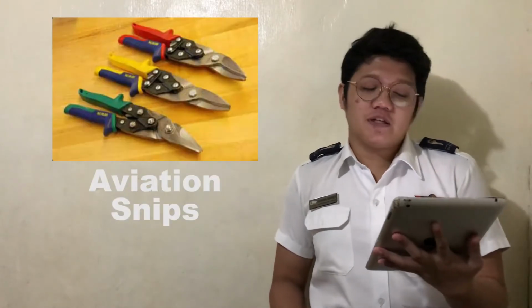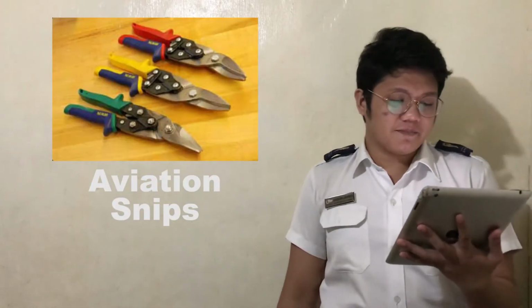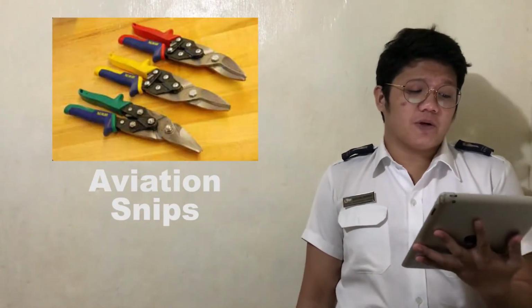Next one is the aviation snip. Aviation snips are used to cut holes, curved parts, round patches, and doublers in sheet metals. Aviation snips have colored handles to identify the direction of the cuts. First is the yellow. The yellow is for the straight line cut. The next one is the green. Green stands for GR, which means go right. And lastly but not the least is our red color. The red color is for go left.